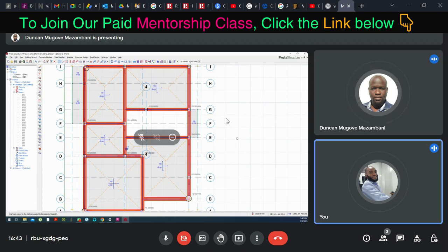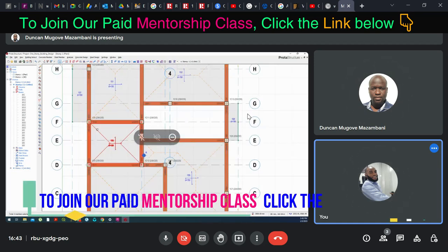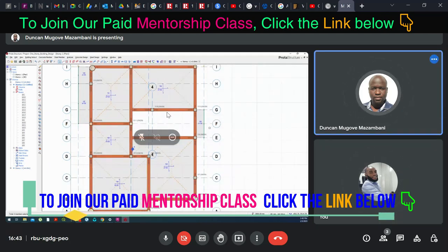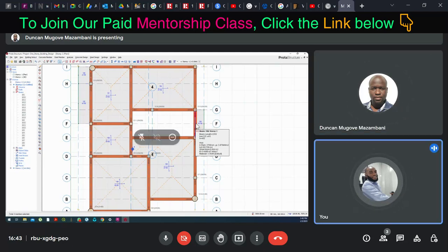So just escape or click outside. Click outside first. Now click on the place where you have cantilever on the beams, and then remove the wall load on the beam around that cantilever area. Yes, because we have already transferred it. Like this beam here. No, this beam here. Yes, that one. We have already transferred that wall load on the cantilever edge. So remove the wall load.